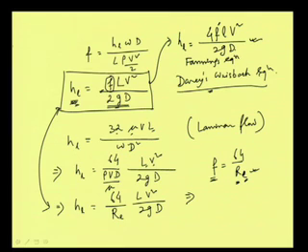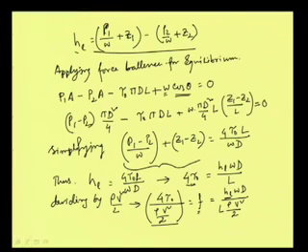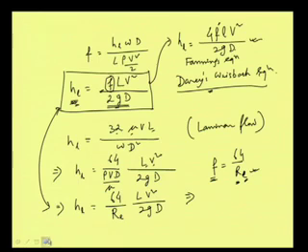Some people prefer to show this 4 explicitly, which is coming here, however some people feel that the friction factor is ultimately a constant, so we can show it just as an f value. So, both the equations are used. I am emphasizing this point because the value of the friction factor is very important.